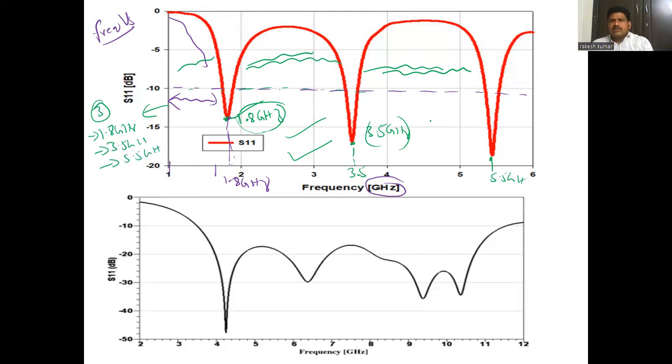So this antenna, if you are getting this type of results, comes under multi-band antenna. So what is meant by this multi-band antenna? An antenna which operates for multiple applications or which operates at different frequencies. Here in the antenna terminology, I have already told that application means frequency. Here it is operating at 3 different frequencies.